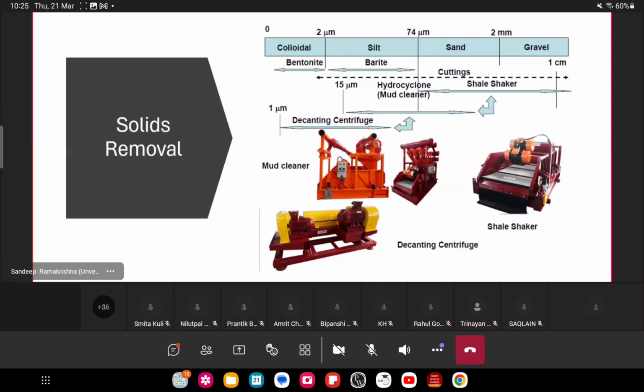I mean, probably we used it in our experiments in the ninth, 10th grade, or maybe in the 11th or 12th grade. After that, sometimes we overlook these kind of simple things. But when you get back in the field, this is where it becomes again and again critical to start doing these fundamental things, fundamental physics and math. So measuring the inner diameter, outer diameter, knowing the condition of your equipment, very critical.